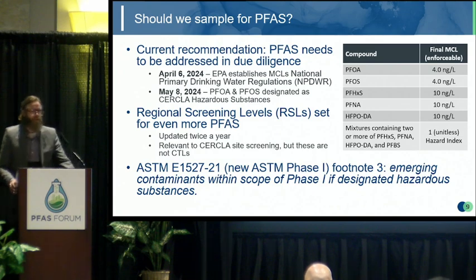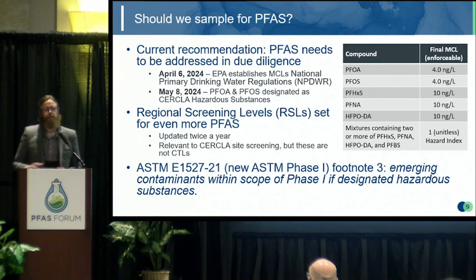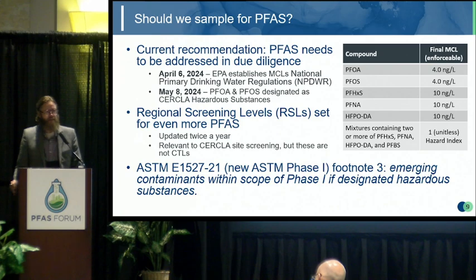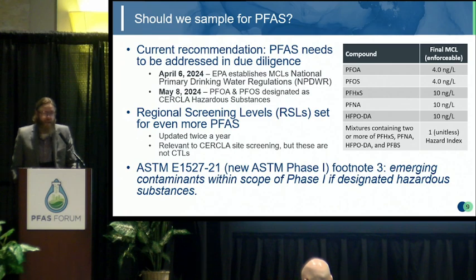So, regional screening levels are not like a CTL. They're used primarily in federal sites to determine the direction to take testing. Screening is, you can think of as, a broader, more general kind of term. So they don't have the force or the use of a CTL. And then MCLs, maximum contaminant levels, are sourced from the Safe Drinking Water Act, and they're groundwater standards. So, while these things circle around something like a CTL, none of them really is a CTL. What we have that's a CTL is the DEP CTL, the provisional CTL, and currently there are sites being assessed, being remediated, being closed using those provisional CTLs.